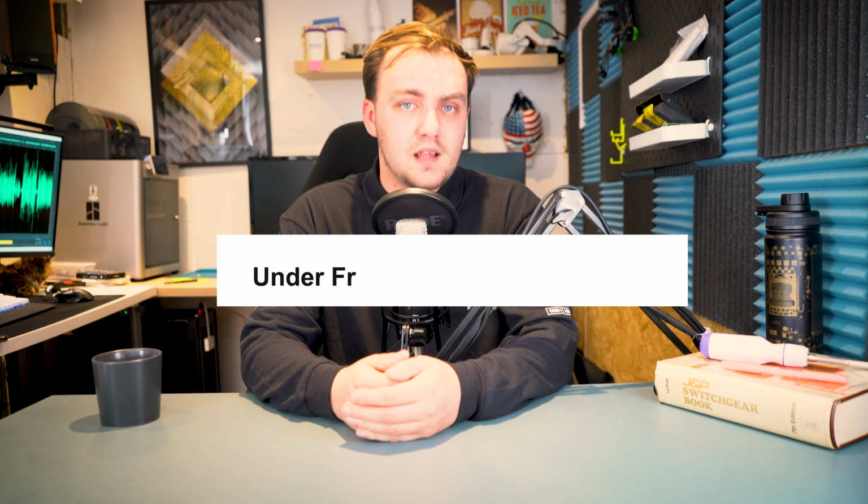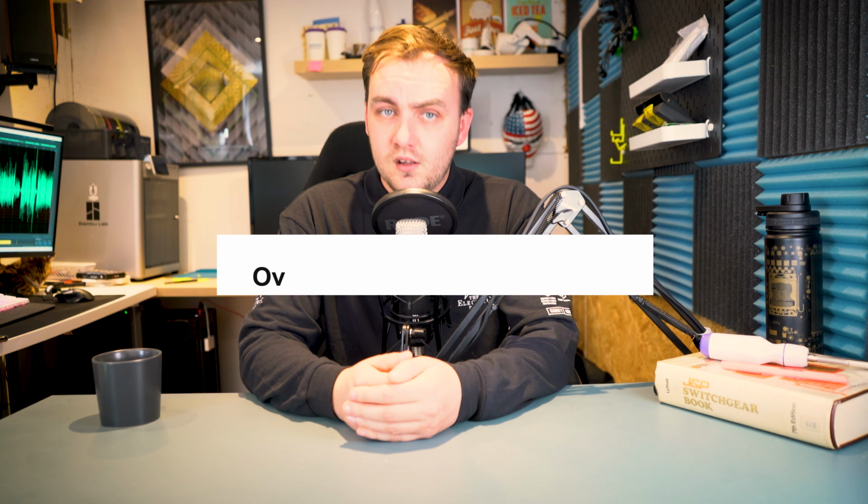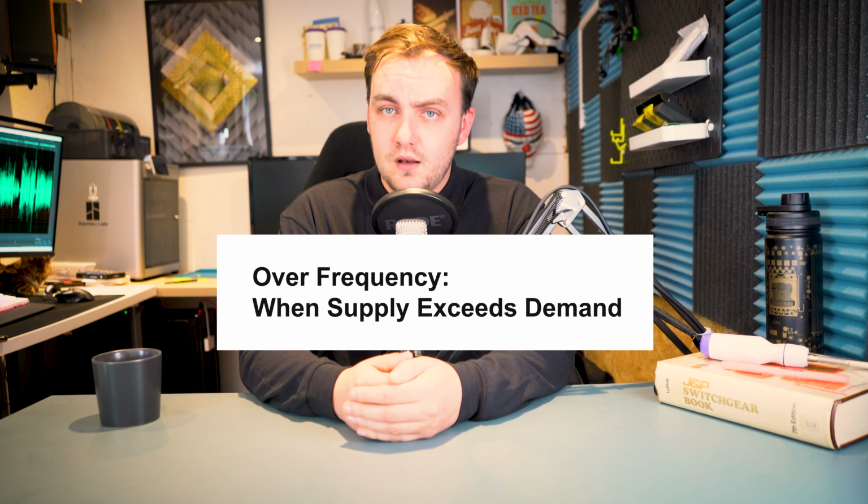We can run into under-frequency situations when supply is less than demand, or put plainly, there's more load than generation can supply. Therefore, more power is being consumed than generated. Over-frequency occurs when supply exceeds demand, or more power is generated than consumed. The grid mustn't deviate from its standard frequency, as this can cause equipment damage, reduced efficiency, or blackouts.